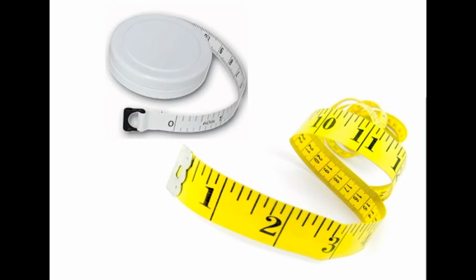And then finally, the remainder of the fabric is drawn gently along the table until the last 3 to 4 meters portion lies flat and free from applied tension, and again the third pair of markings are made over here. And using a ruler or tape, the fabric length and width are measured accurately, making sure that there is no tension exerted on the fabric.